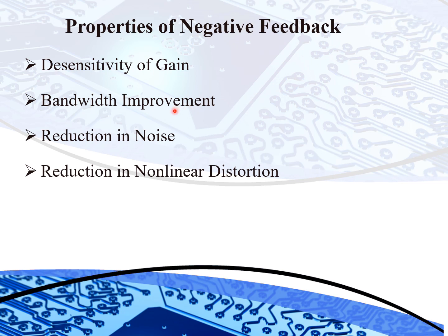The second property is bandwidth improvement. We can extend the bandwidth for a large amplification factor. The third property is the reduction in noise, or noise sensitivity, which actually improves the original output by reducing the noise. And the last property is the reduction in nonlinear distortion.